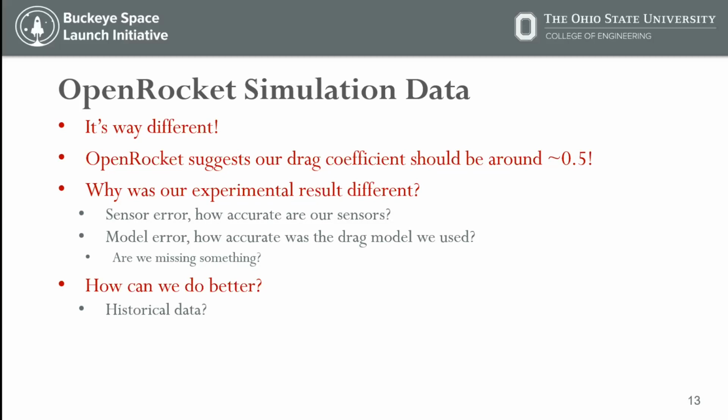And if your sensor's not accurate resolution-wise, it's kind of like trying to measure millimeters with an inch ruler: you're probably not going to be very accurate unless you understand the relationship between those. Say your ruler only has a resolution of 1 inch and you're trying to measure quarters of an inch, you might be able to do it, but you probably won't be very accurate doing it.